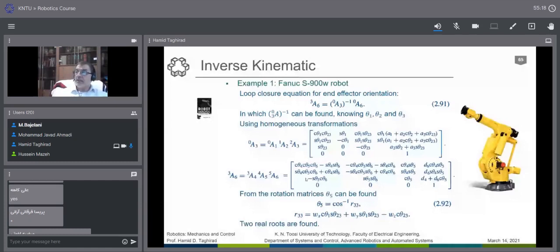You can see that R33 is a function of theta 1, theta 2, theta 3, Wx, Wy, and Wz by this manipulation. So theta 5 could be found here, and cosine gives you two solutions again. Up to here we have 4 solutions, 2 of them were practical. Now in terms of the orientation, again we have 2 solutions here as well.